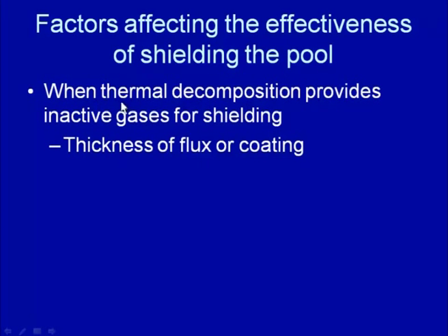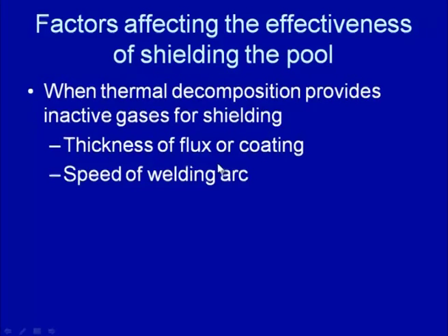When we use the thermal decomposition approach, like in shielded metal arc welding, where heat of the arc is used to decompose the hydrocarbons and develop inactive gases for shielding, the amount of flux present in the consumable electrode matters. The greater the amount of flux, the more decomposition of the hydrocarbons, and the greater the amount of inactive gases generated to provide effective shielding.